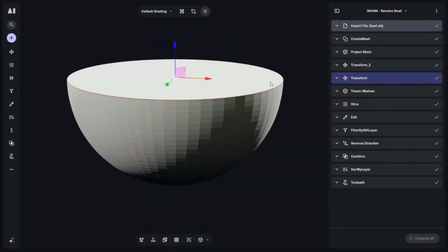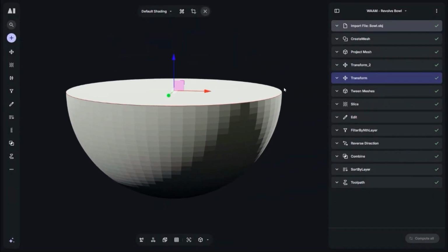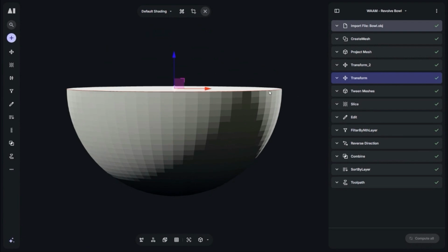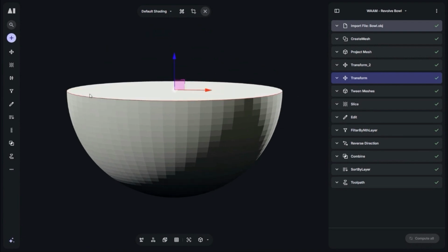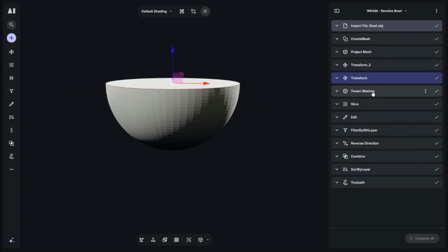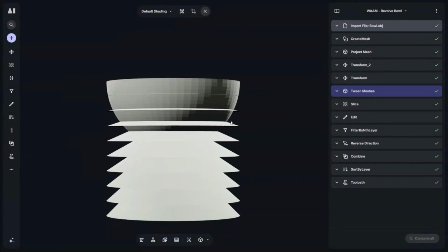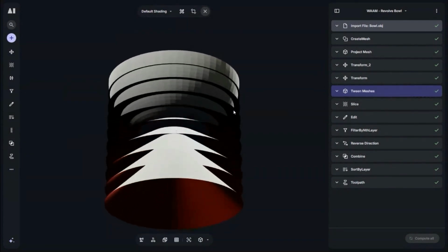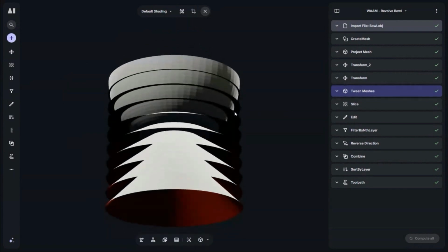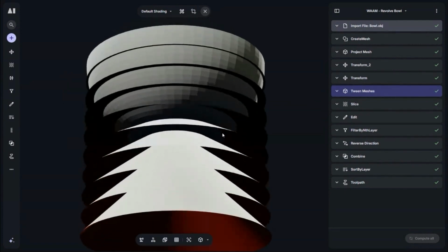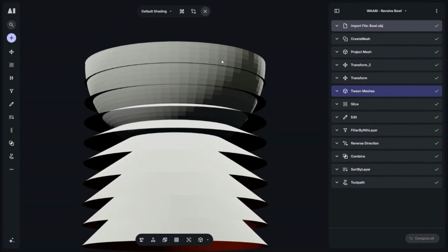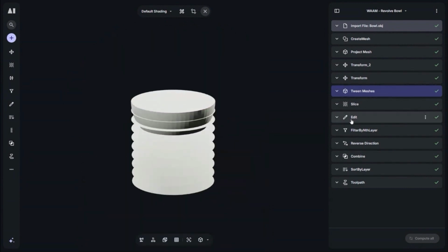And then the other guide is this circle here. This is fairly a bit more obvious as to how it's working. It's just a flat circle. So the shape of the bowl, it's flat, so the layers at the top are going to be nice and flat. And with those CAD options in the software, this is essentially how the non-planar slice works. It will tween these meshes as guides. Of course, much finer than this, but you can see how our layers are going to gradually conform to horizontal, and they'll start smaller here.